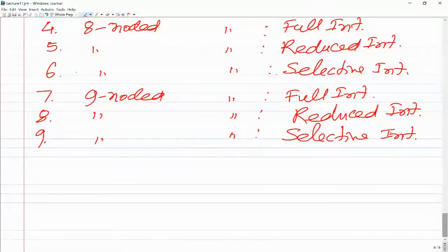You use an additional stiffness matrix to overcome hourglass, and for high strain rate problems you use an additional damping matrix to overcome the hourglass problem if you are using the selective or reduced integration technique for thick plate problems. So that is how it is overcome. This was one method. There are two other methods. The second method, as I said, is to overcome the locking.